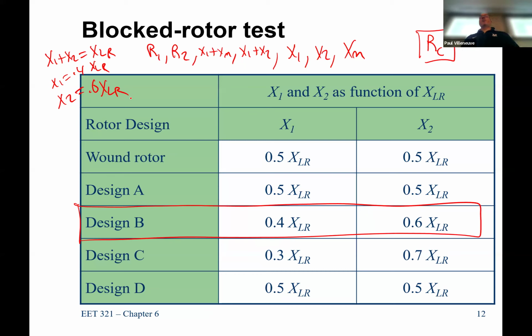So running a motor for 5 minutes at nearly lock rotor current is a sure way to spell doom for that motor. If you get it up to speed quicker, you don't need as big of a rating for the motor, and you might have a little bit of an efficiency penalty because you're not running at the same level of slip. But instead of taking 5 minutes to get up to speed or upsizing the motor, I can go with the minimum motor size that I need, and then just run it at 1 minute because it gets more torque available, and spins up faster.